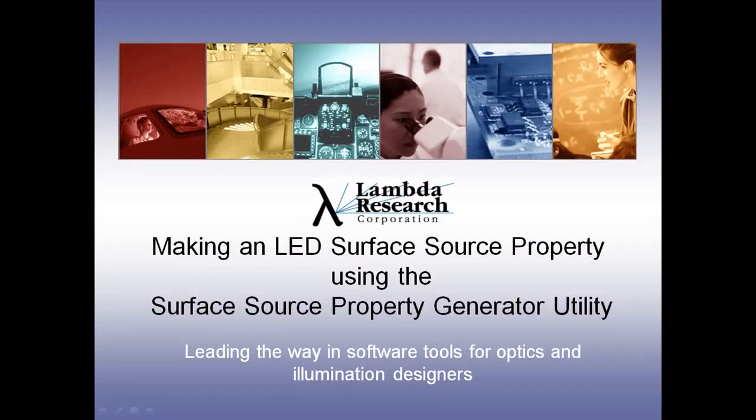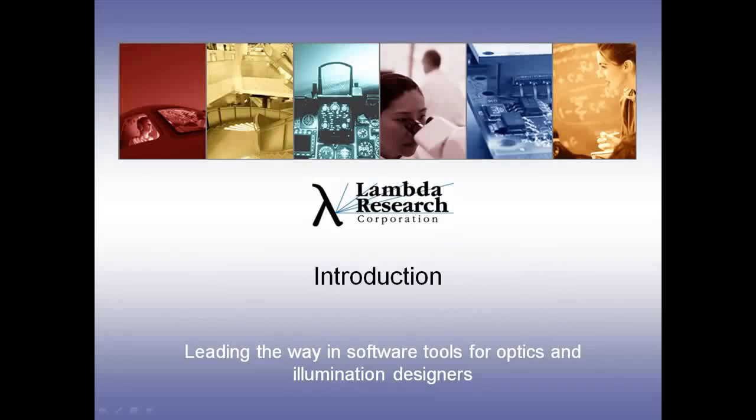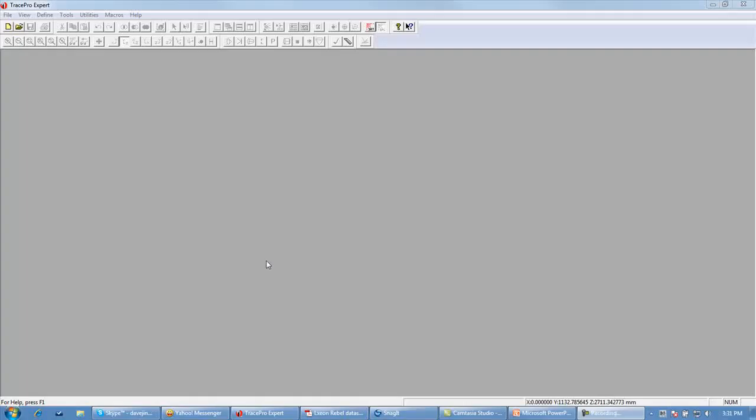In this video, we'll show you how to make an LED surface source property for TracePro. To do this, we'll use the TracePro Surface Source Property Generator utility and an LED datasheet. The first step in the process is to open the Surface Source Property Generator utility from the Utilities menu of TracePro 7.0.